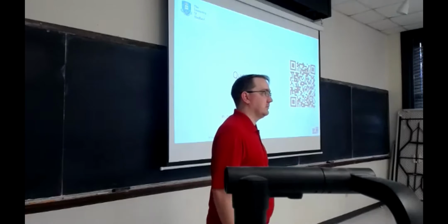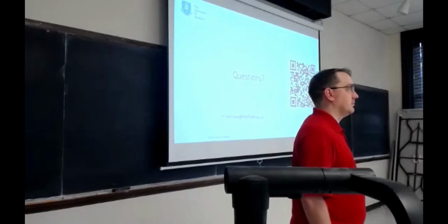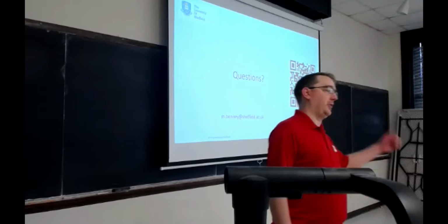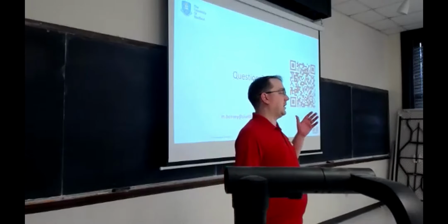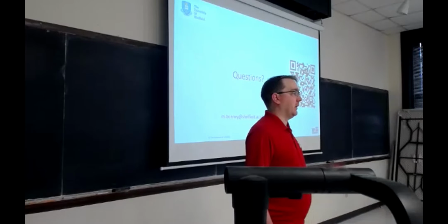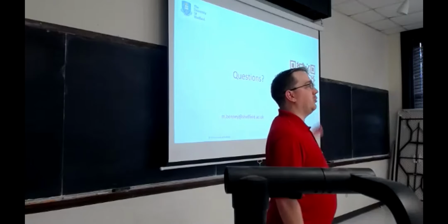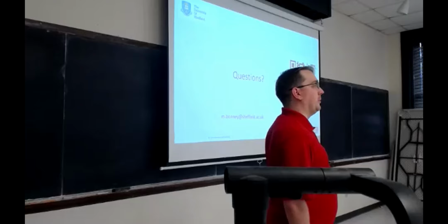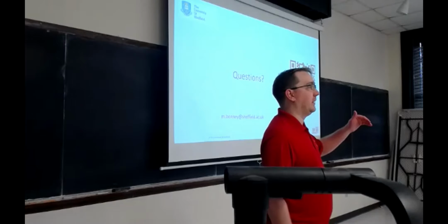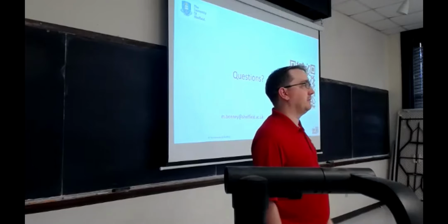I see this is a user interface for FEA, right? So when you click submit, how long will it take? It depends on the analysis. For that particular analysis, about 90 seconds, 2 minutes. 90 for what? For temperature or stress? This is just eigenvalue analysis. But you can do whatever analysis. Essentially what that run button does is it goes to command prompt and tells Abaqus to run this analysis. So however long it would take to run in Abaqus, it takes the same amount of time here.